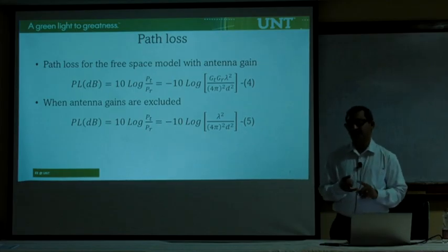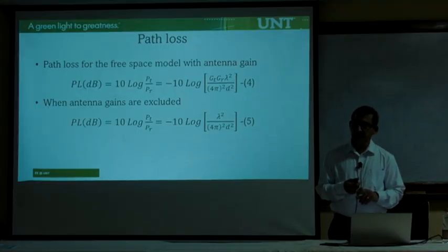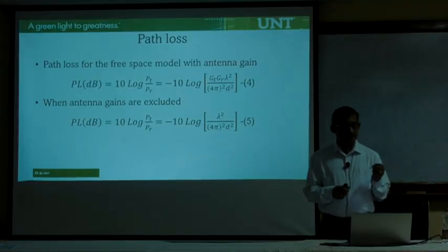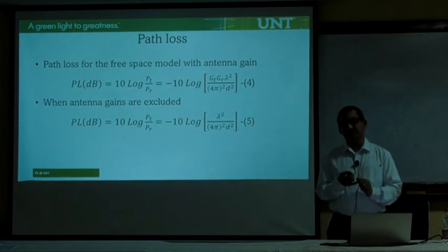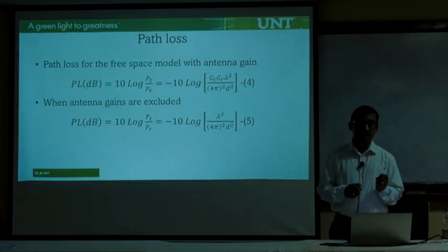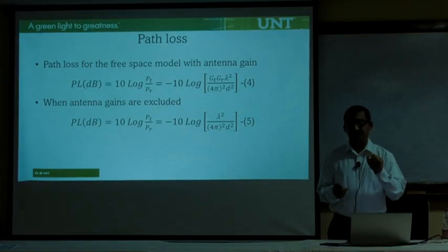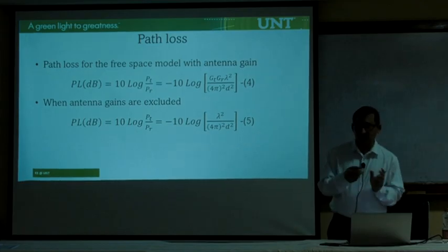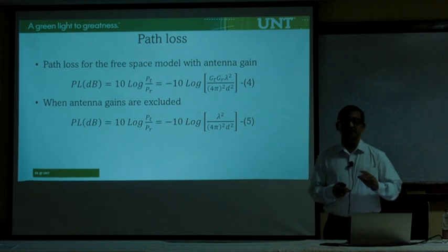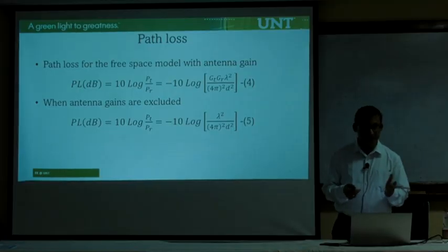We say dB, sometimes we say dBm. What's the difference between dB and dBm? M refers to milliwatts. You are using power in milliwatts. So dBi is there. dBi is used for antennas, with reference to isotropic; I stands for isotropic antenna. In the same way, dBm refers to milliwatt as a reference. dBi refers to antenna gain actually, so that refers to what the channel gain is with reference to an isotropic antenna.